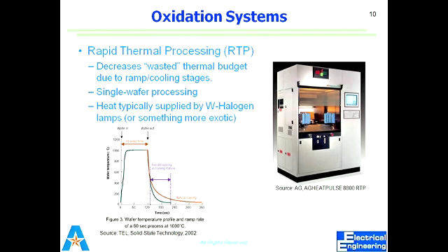But you know that the quality would be better. But what would be the problem with dry oxidation? What is the limitation of dry oxidation? That is actually the thickness, that is the oxidation rate. The oxidation rate is very low, so you cannot grow a thick layer of oxide. If you want to grow 1 micron, you cannot do it with dry oxidation. You will have to go to wet oxidation. But yes, he is right that whether it's a horizontal or a vertical furnace, you can use both dry or wet oxidation.